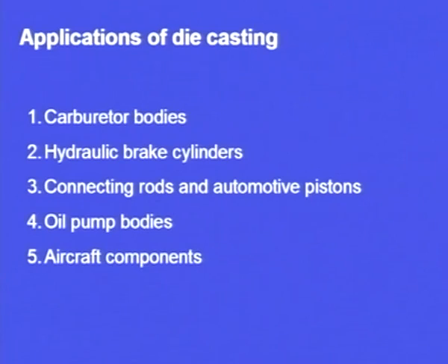And what are the applications of the die casting? Carburetor bodies of the automobiles are made by die casting. Hydraulic brake cylinders of the automotives are manufactured by die casting. Connecting rods and automotive pistons are manufactured by die casting.